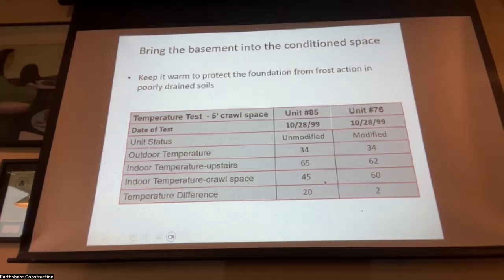That doesn't really say how much heat he's losing. No, but it gives a sense that you're only 2 degrees different than the living room. So you don't have a big loss through the crawl space, it's all below grade. And where it isn't below grade, it's insulated. So that's why from the bottom of the subfloor down to a foot below grade always worked out to be the best return on the investment. That's the question, like, how much value is it insulating deeply below ground? You can calculate that, but what I'm saying is it never was enough to make it worth risking the foundation.